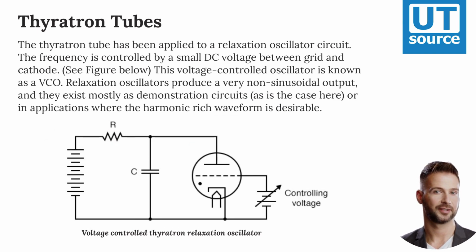As the AC supply voltage climbs from 0 volts to its first peak, the load voltage remains at 0, no load current, until the threshold voltage is reached. At that point, the tube switches on and begins to conduct, the load voltage now following the AC voltage through the rest of the half cycle.